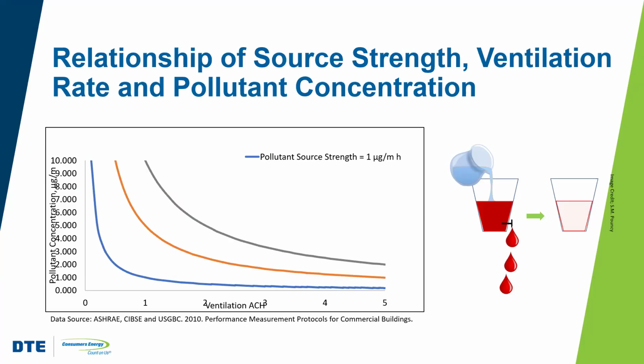So to help get rid of them and dilute that air even further, we also bleed off a little bit of that fluid, bleed off a little bit of that air. And then you can see the difference here. Instead of having the dark red cup of fluid, you've got a lighter red, a more pink cup of fluid.